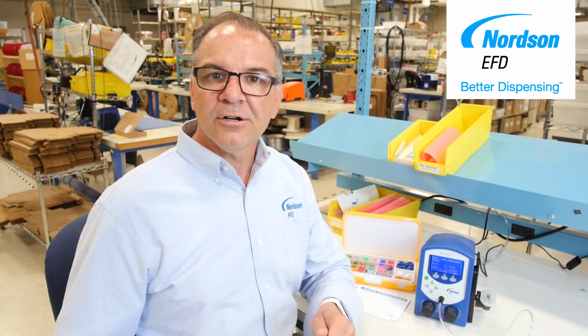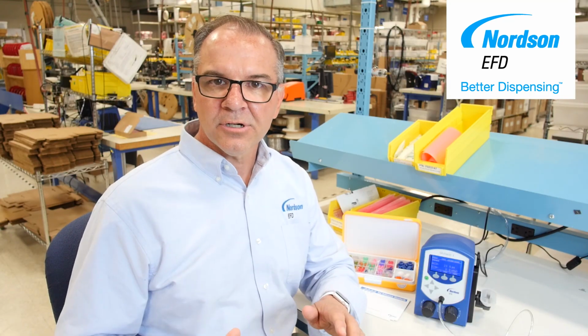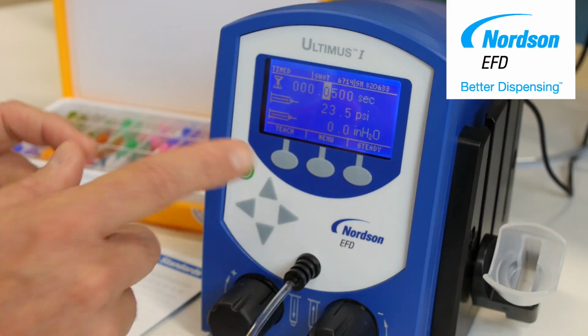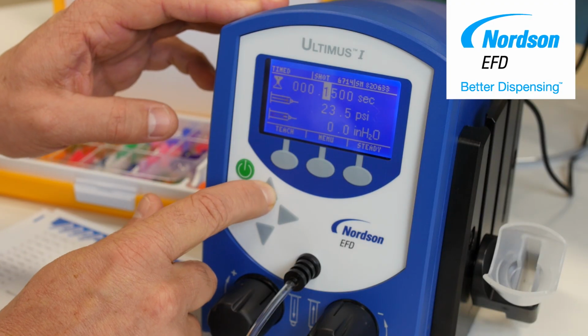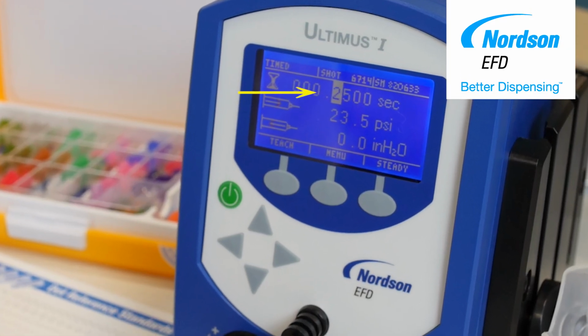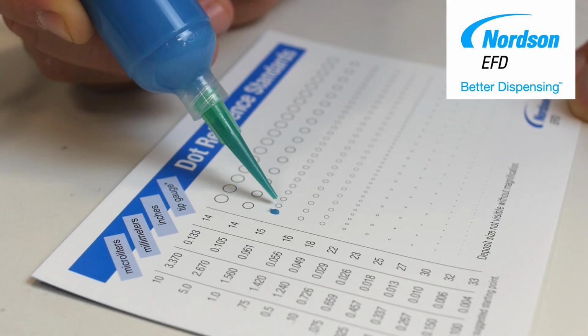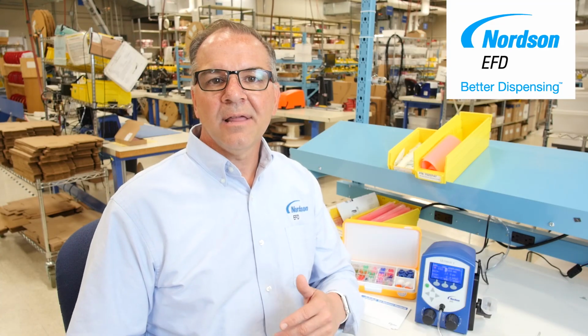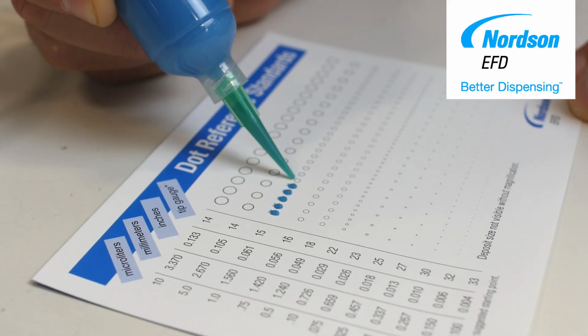Now that we've selected our tip and established our pressure, we're going to work with the timer to control our dot size. Start off by setting your timer at 0.250 seconds and see what kind of dot that gives you. Then increase or decrease the timer based on the size of the dot that you need.